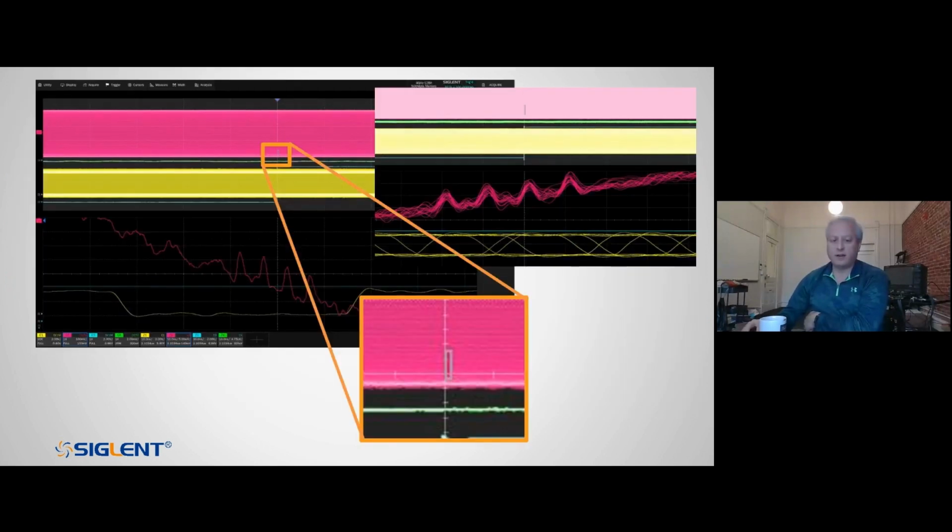To summarize that, this is the area we've zoomed in on, that little gray box in the other signal. So that silver rectangle there is the blown up area on the bottom of the screen. So just like memory and sampling rate allow us overhead to zoom in on the horizontal, excellent noise, isolation, and resolution allow us to zoom in vertically as well. Then we can use features like persistence mode and history to visualize the signal changes over time. Like there, I captured a persistence mode capture in the top right.